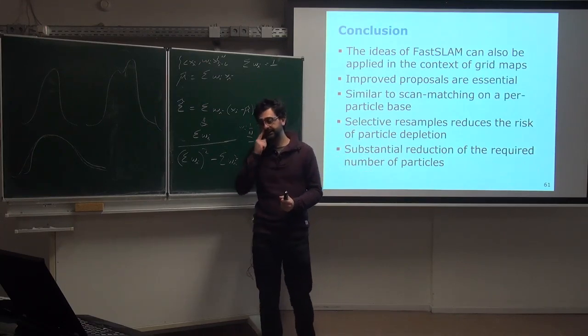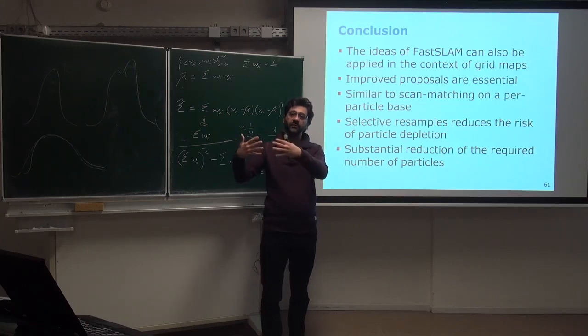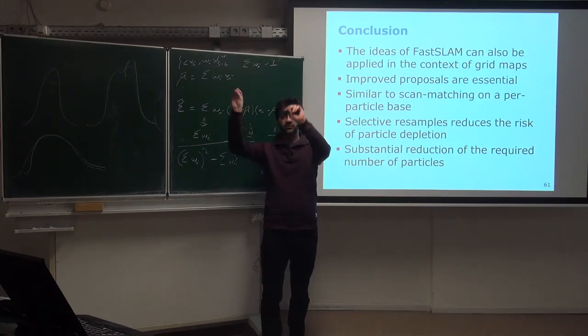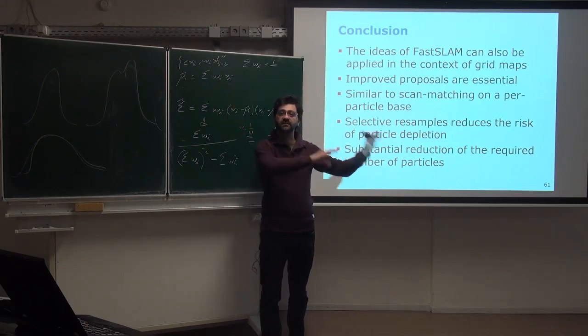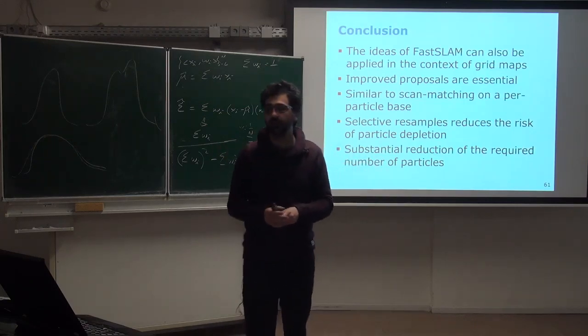Or we have seen that you can do it differently, where we do, again, another two-step procedure, where we do sampling from the odometry. For each sample, we do a scan matching, and we use exactly these scan-matched points as our samples for the particle filter. Okay? So these are the two ways we can do this.